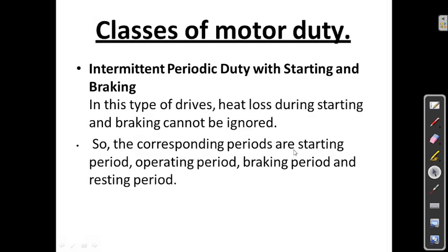Again, intermediate periodic duty with starting and braking also. In this type of drive, heat loss during starting and braking cannot be ignored, because both starting as well as braking produce heat loss. So, the corresponding periods are starting period, operating period, braking period and the resting period. This is called intermediate periodic duty with the starting and the braking.